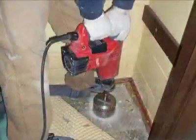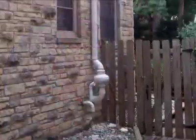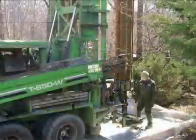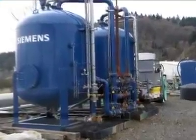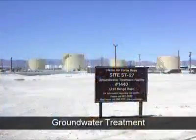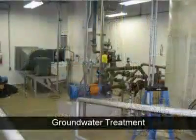And installing subslab depressurization systems. These are similar to systems proven effective at preventing radon in soil gas beneath a building from entering the building. Other types of corrective actions may include installing remediation systems designed to remove or reduce the contaminant source. These systems can include groundwater treatment. This is often a very common type of corrective action, as contaminated groundwater is often the source of soil gas